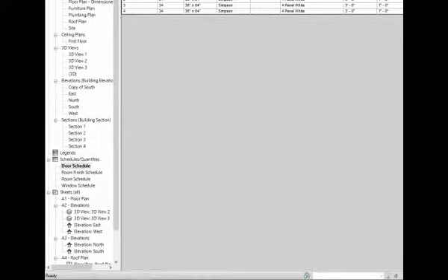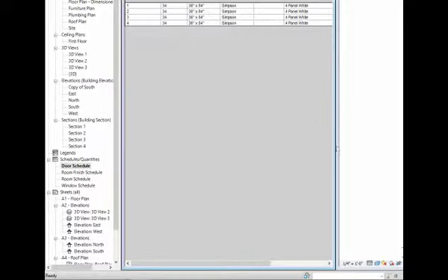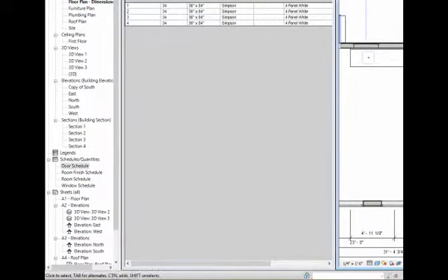View, view, view. Tile right there. Okay, so here's door number 4 over here. This door number 4 refers to that door number 4 in the schedule. So if it turns out, oh, the exterior doors I'm going to leave 36. How about these interior doors, the bathroom door, for example? I might not need a 36-inch door. If I want to change that to a 32-inch door, which is probably sufficient. Okay. Notice door number 1 over here, I changed it. It's also changed over here in the schedule, so it's 32 by 84. Maybe the same thing for door number 2 here.